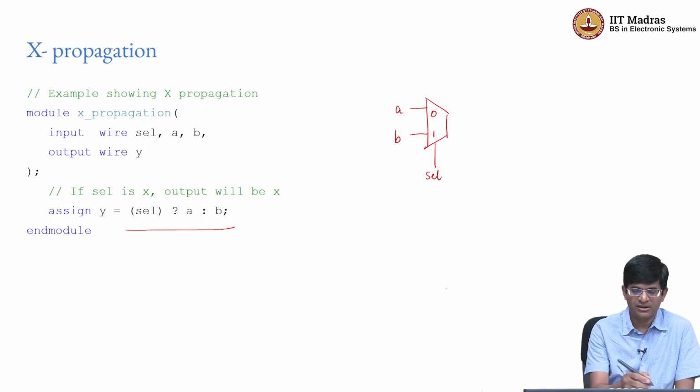And keep that in mind, this notation by itself is just the so-called ternary assignment operator in Verilog, similar to the thing in C. The fact that it corresponds to a multiplexer is an observation we have made. It's not a fundamental rule of Verilog. Verilog does not say that this is actually a mux. All it says is this is a ternary operator. I am drawing a mux because that is our normal interpretation of what a statement like this looks like.